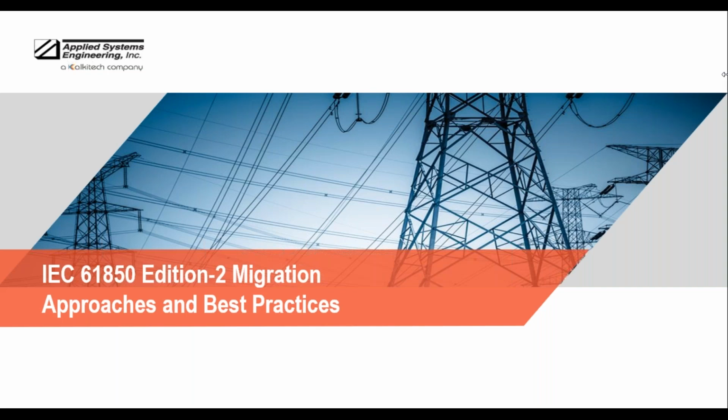Today's topic: Migration to IEC 61850 Edition 2, Approaches as well as Best Practices. This webinar would detail the key requirements in planning and executing IEC 61850 Edition 1 to Edition 2 migration for customer products and services. The talk aims at covering the major differences between Edition 1 and Edition 2 of the standard, as well as the key functional areas of Edition 2 that a migration needs to address. This session also would cover the additional test cases that need to be implemented, as well as the best practices to be followed.